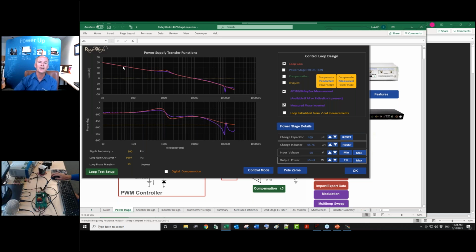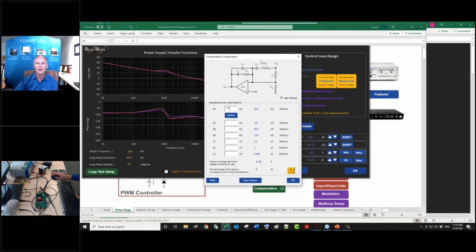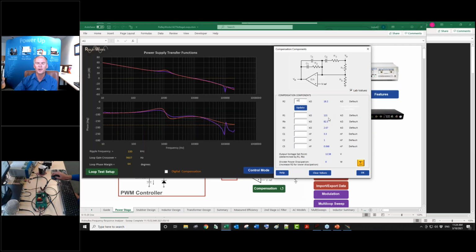So here's what I'm talking about. My loop is now a verification that this measured gain tells me, yeah, you built it like it was supposed to be built. You had these compensation components, right? There's no way you didn't put these values in. Otherwise, you wouldn't have hit this asymptote here, and the phase at that point. But we don't know about the Q. So, different things you're using the loop for.